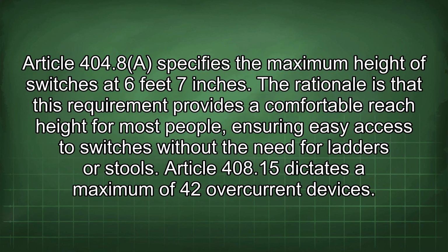Article 404.8 specifies the maximum height of switches at 6 feet 7 inches. The rationale is that this requirement provides a comfortable reach height for most people, ensuring easy access to switches without the need for ladders or stools.